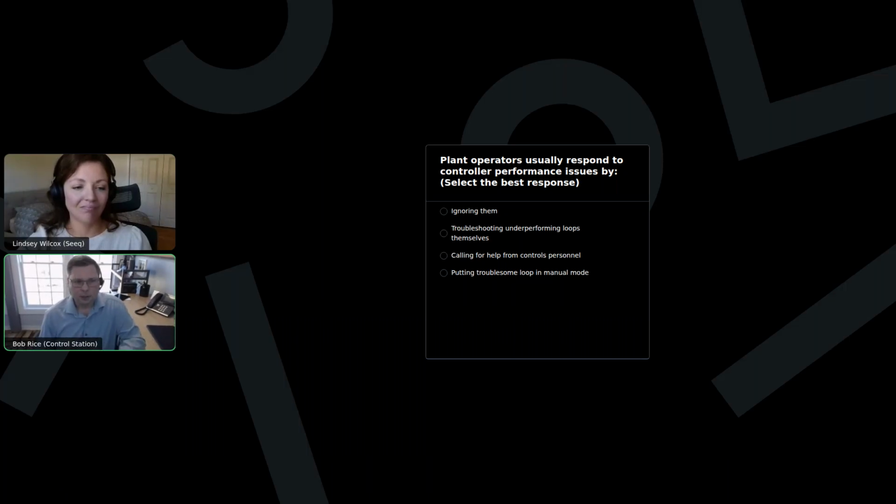Lindsay, when you would go into plants or talk to staff, what is the troubleshooting process at sites that you see now? Does it tend to be more internal or external? What are some examples there? Yeah, maybe surprising, maybe not surprising, I would say I frequently would see operators putting troublesome loops in manual mode.